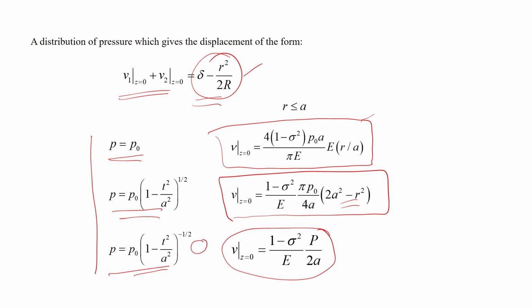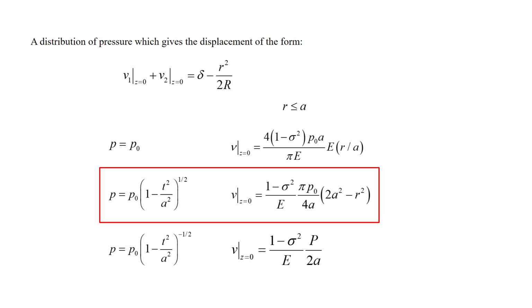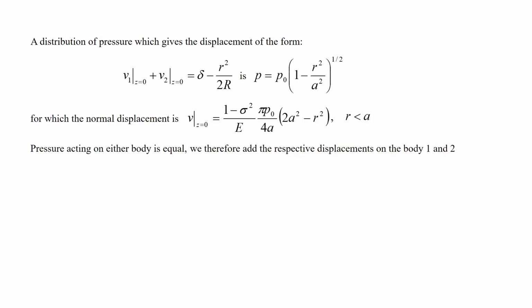So, what it means is that the load distribution at the contact area for this case of two solids of revolution in contact is essentially p equal to p 0 into the square root of 1 minus r square by a square. That is what we have to consider here, and let us say V defines the total load. We will soon see how it happens, and then we can compare this relation with this relation over here.